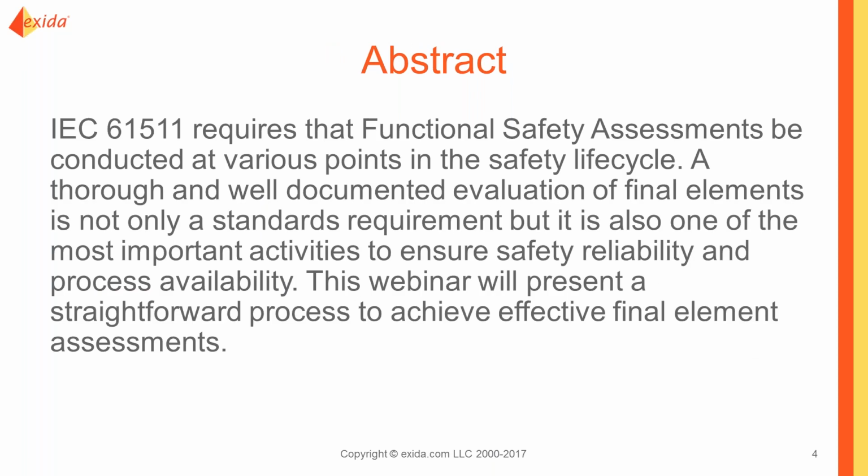So our topic today is functional safety assessment of final elements. IEC 61511 requires that functional safety assessments be conducted at various points in the safety lifecycle. A thorough and well-documented evaluation of final elements is not only a standards requirement, but also one of the most important activities that can be conducted to ensure safety, reliability, and process availability. And in this webinar, we'll take a look at a straightforward process to achieve effective final element assessments.